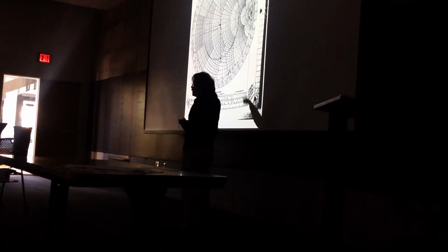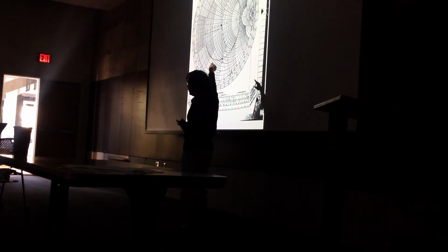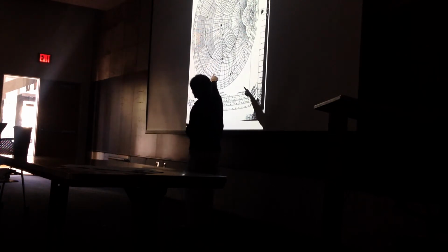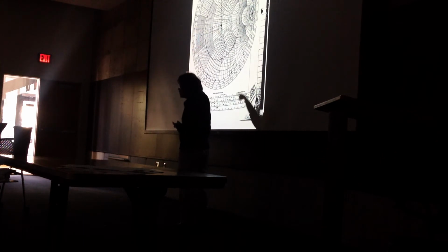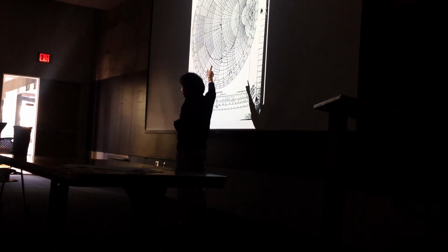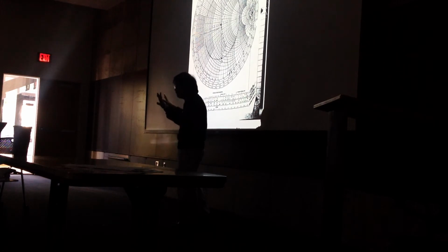Once you find that point, take out your compass. Make the center the origin and the constant radius passing through that point, ZL. That is the constant circle which I drew. Look at that constant circle. In that circle, every single point is an equal distance to the origin. In other words, your reflection coefficient magnitude is the same.